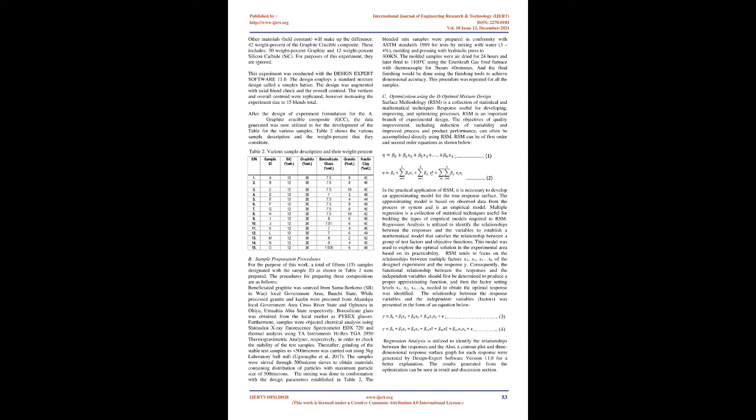1. Invented a new and useful improvement in methods of making graphite crucibles. The object of the invention is to provide a graphite or clay crucible or pot which has a lasting and adherent glaze on its surface, and which is of superior quality and has a longer life than such crucibles or pots as heretofore made. The work discovered that if certain non-ferrous metals in a finely divided metallic state be incorporated in the clay or mixture of clay and graphite from which the crucible or pot is formed, it causes the formation of a glaze which is very adherent, which does not readily spall off, and which, therefore, protects the body of the crucible or pot and increases its life.